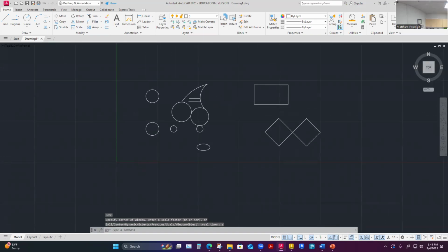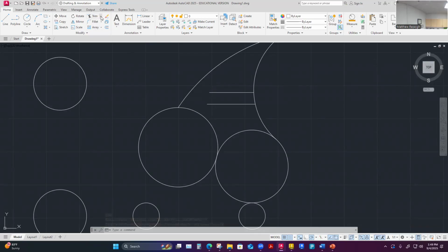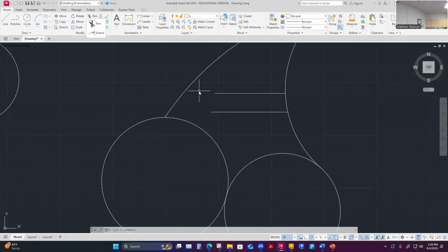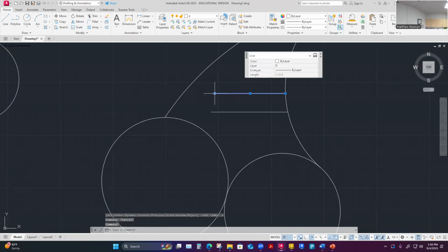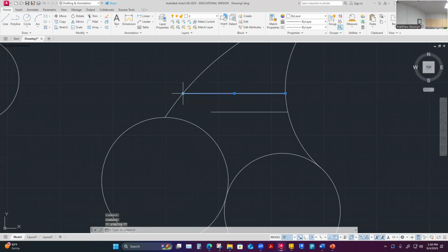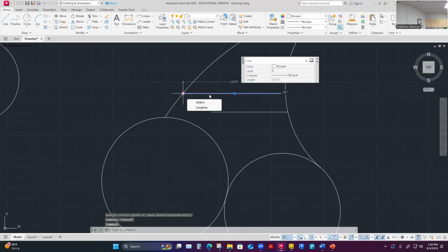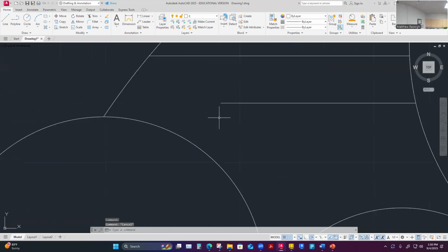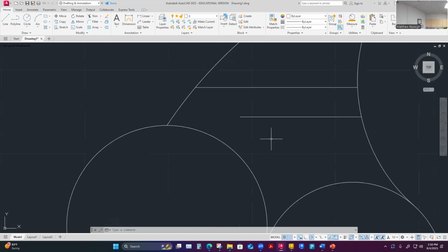What I was going to show you was the opposite of trim, which is extend. If I have something that I needed to actually go over, like I want this line to extend, yes, I could come in here and select the line and grab the grip and then also use that intersection. I could do that a little bit manually, but these lines have grips. They are meant to be gripped. And as long as I have my object snap tracking on, I can keep it in alignment and not pull it off. The problem with grabbing grips and moving it is it will potentially allow you to pull something out of alignment. So if I needed to maintain this truly horizontal line, extend is a really good option for that.